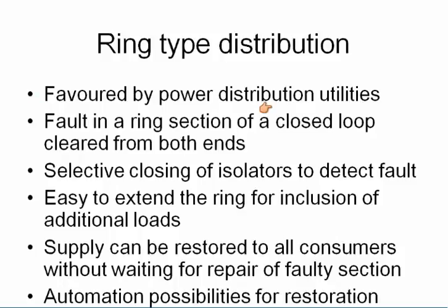So it's the preferred approach by utilities. You can have selective closing of isolators, detect faults, easy to extend the ring for additional loads. Supply can be restored to customers without waiting for the fault to be repaired. Automation possibilities for restoration. You can have automatic schemes.